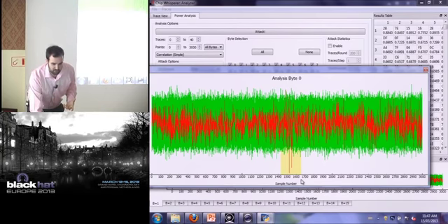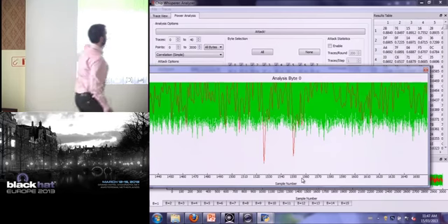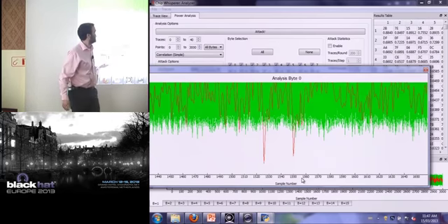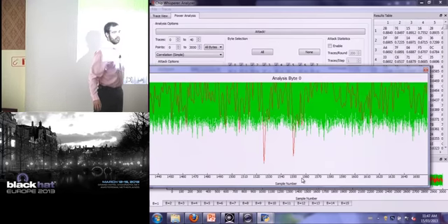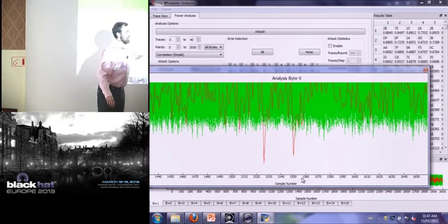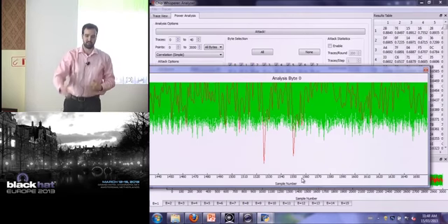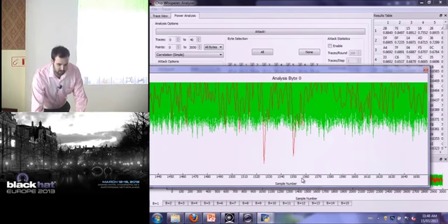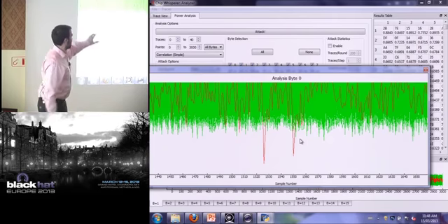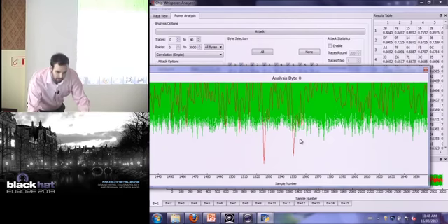And because it's software, you may actually see it happen a few times because perhaps this is a subroutine. The SBox is being looked up here from memory, and then later on, it's passing that SBox output somewhere else, or it's passing it to one of the MixColumns operations. So that's why you may see multiple.